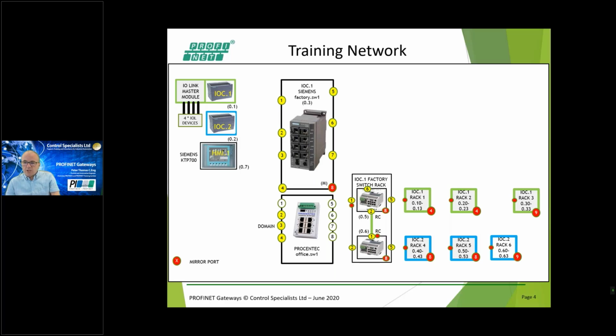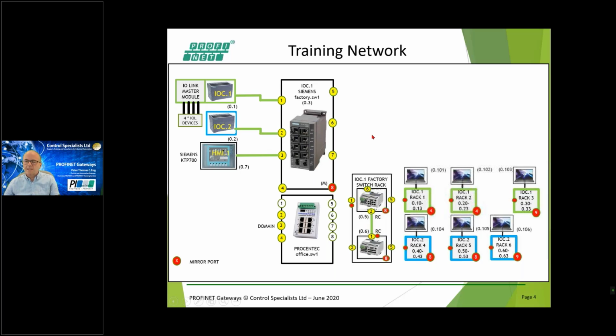We've got a couple of switches there. And from last week and the week before, you'll realize that we can actually connect PROFINET devices up without a switch, but it's not really a good idea. And we mentioned the idea of using conformance class B switches for ongoing support and qualification. So basically, the way in which this is connected up, we connect our devices to the switch. We then make a connection from the switch and we start to build up to the various devices using copper,